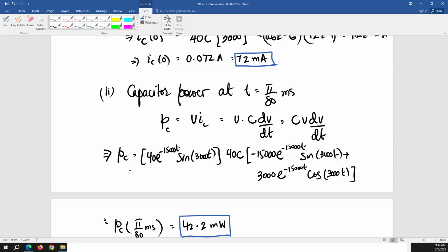Again, the breakers that we have usually have a response time that is not fast enough compared to the time it takes for the energy to deposit that charge. That's why even with the fastest breaker, generally you end up burning stuff. For regular interruptions, yes, the breakers can handle that. But with a lightning strike, many times breakers cannot handle it because their response time is not that fast.